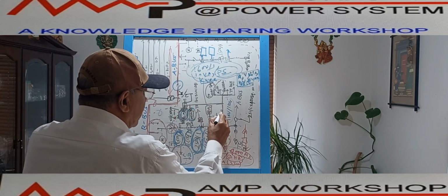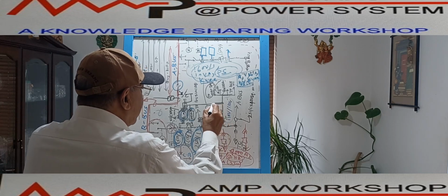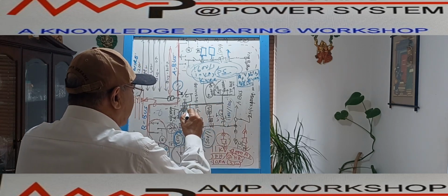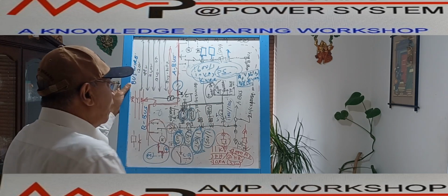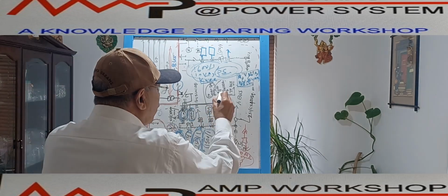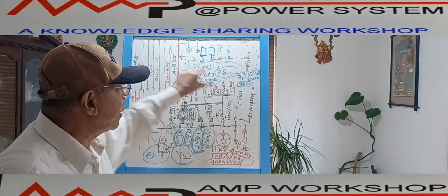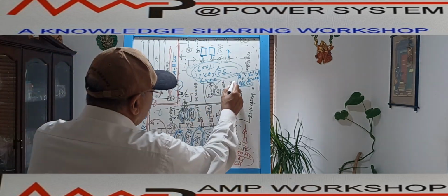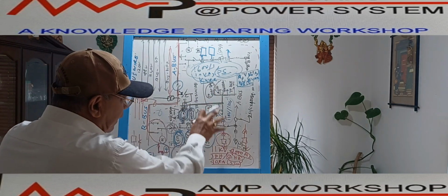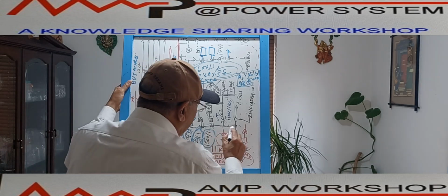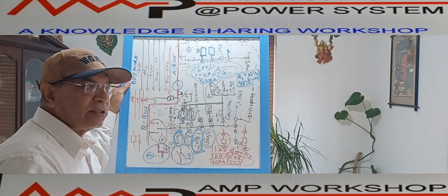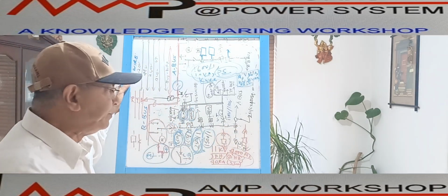There is an MCB over here. After the MCB, one tapping is coming over here to supply the multifunction meter and this relay, and the other tapping is going to the outside for the synchronization, AVR. All this will go over here. So this also has to be shown. And then it is going to the terminal from where the generator is to be connected, right?